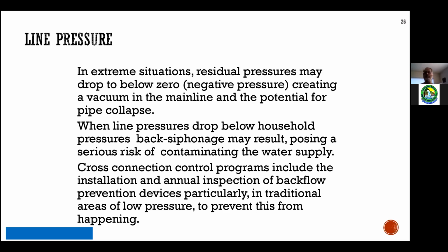We would actually forbid other departments from using water. You can't hook a street sweeper hose up to fill a tank or a sewer flusher because of the potential for dropping the energy to an unacceptable level. So we said you can use the fire hydrant over in this neighborhood where we have lots of elevation and lots of energy available.